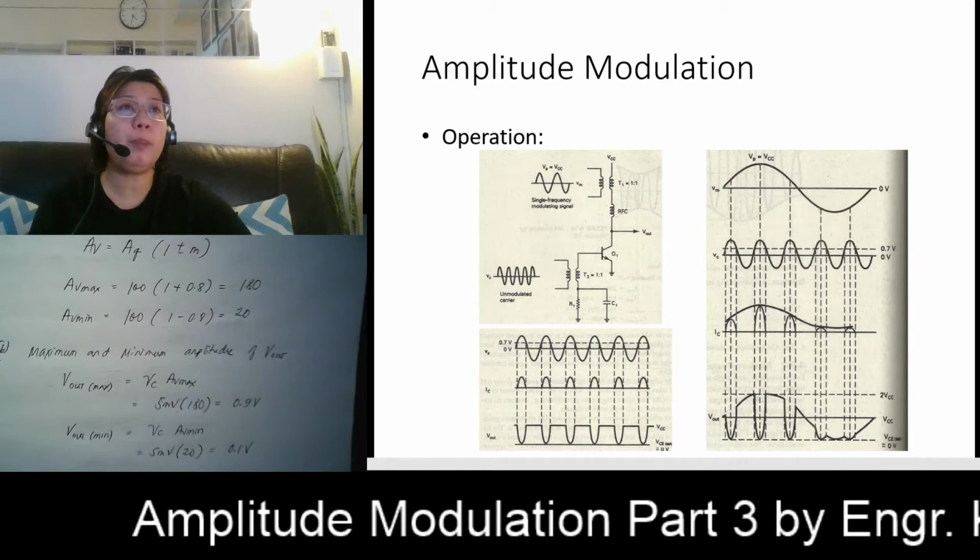So when we have a peak change in your carrier voltage amplitude, that is equivalent to VCC. Your output signal also resembles a half-wave carrier superimposed onto a low-frequency AC intelligence signal. In this case, transistor Q1 is operating nonlinearly.